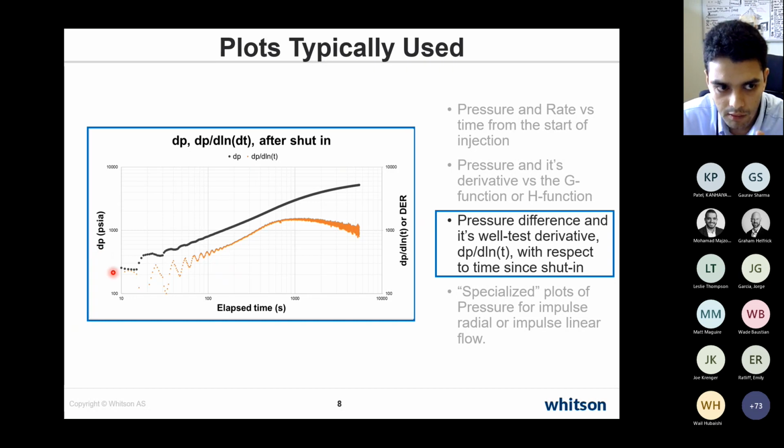And I see that since there is leak-off, the bottom hole pressure reduces, so the delta P goes up, and we can then look at the derivative to analyze these transients. So in this derivative, we can see that the peak at dP/dt is when the fractures have closed, and beyond that, we have the post-closure transients or after-closure transients.